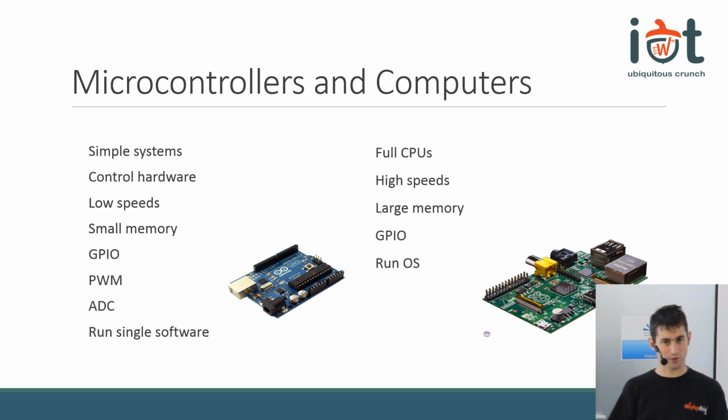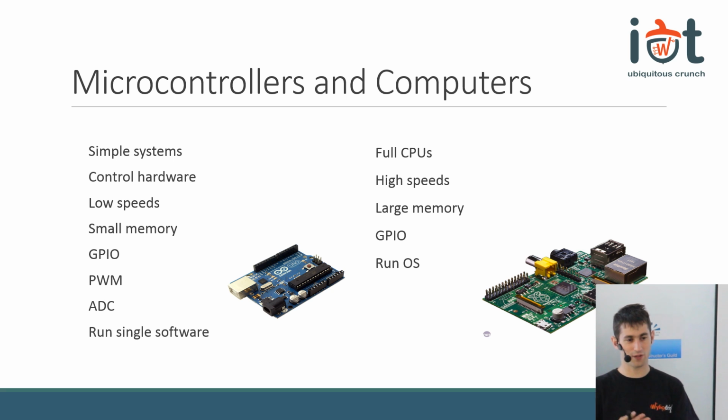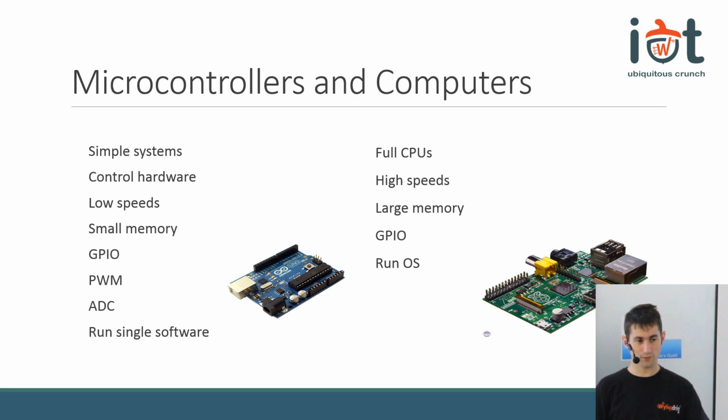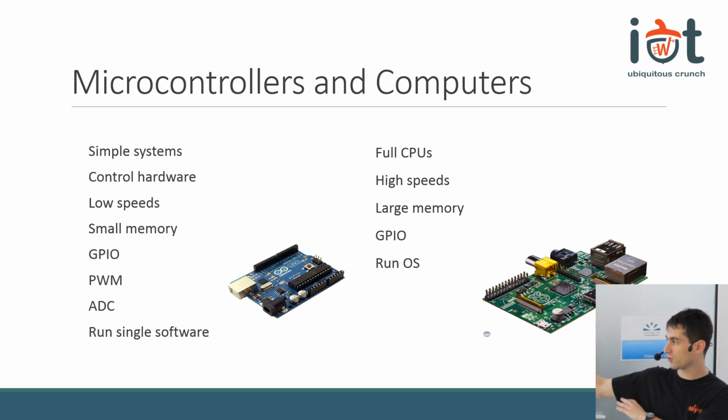No way the board is real time. Your program is one of the many programs that the operating system runs, plus you have an operating system that needs to run drivers. So you cannot predict when something is going to be executed. There's no way to have a fixed delay, so you cannot sample some data with a very clear delay. The best that we could do was tens of milliseconds, while on microcontrollers you can do it with a precision of tens of nanoseconds. Is it clear? So microcontrollers are really good in controlling hardware, while computers, like embedded boards, are really good in processing. So the combination of the two is the solution.